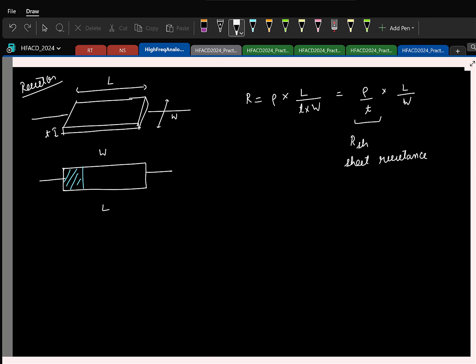Yeah, strictly speaking it is ohms, but typically we say it as ohms per square. To denote that, it is basically the sheet resistance. And the idea is, if you know the sheet resistance, you find how many squares are there within this. Sheet resistance times the number of squares you have is the total resistance. That's all. And again, if you want to know typical values, it can vary anywhere between 50 ohms to 100 ohms per square. It again depends on the particular process.